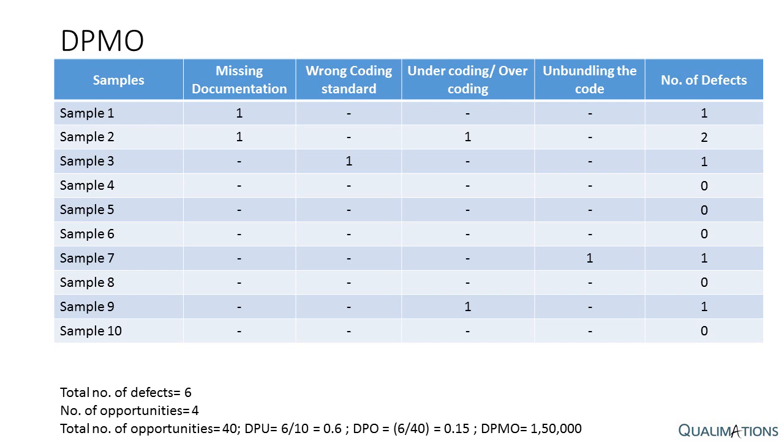Defects per million opportunities constitutes a standard of measure that correlates failures of expected norms in any process. One failure per every million normative outcomes constitutes one DPMO. You can also use the DPMO to analyze the quality and stability of your production or new product introduction process. In a new product environment, the DPMO levels can be used as a trigger to determine if the production process of a new product is under control and ready to be transferred to production.